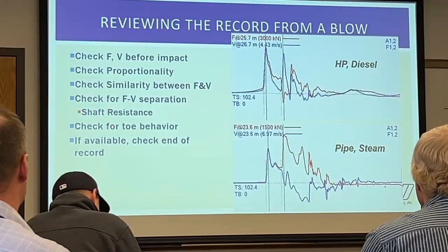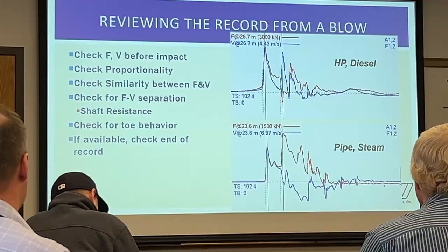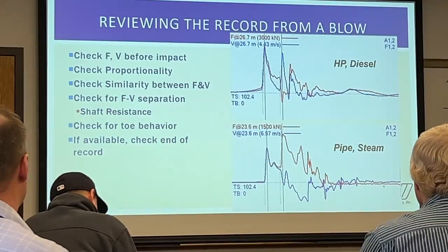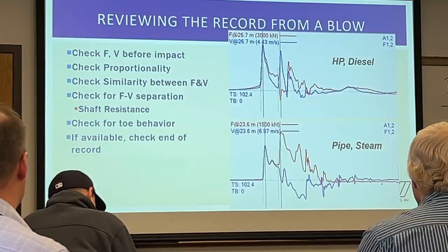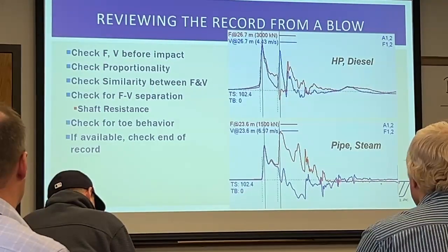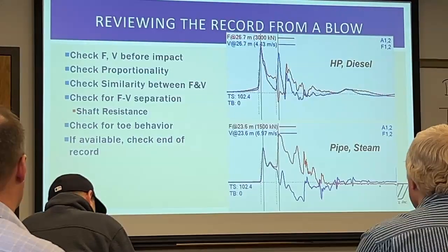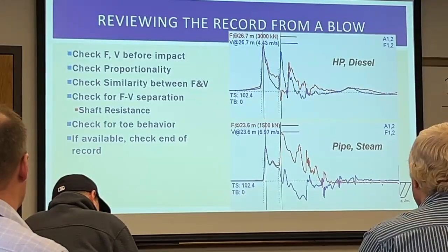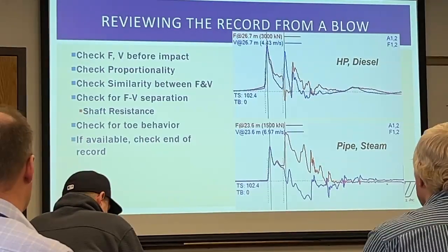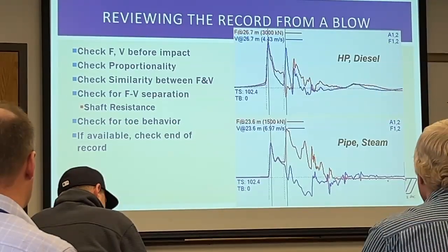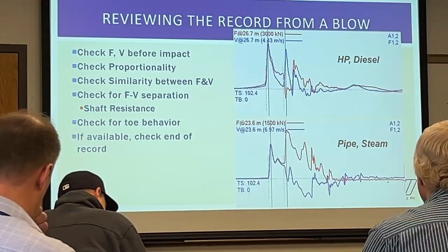And so when we get to some of these pneumatic hammers that we see for guardrails and solar panel farms, where they're driving piles at 300, 400, 500 blows per minute, that's where we may actually get multiple blows in the record that we keep. That becomes a much more difficult thing to analyze. But generally speaking, up to about 200 blows per minute, which is most double-acting diesel hammers and most hydraulic hammers, there is enough of a quiet period before the next blow that we can analyze things well.